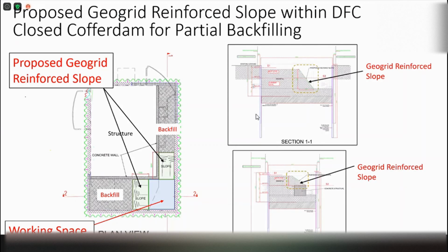So in this project, we are actually required to build a water pipe in the marina area. So this is actually part of the Marina East Desalination Plant project, where we actually have to do a lot of temporary excavation work for pipe laying. So in one of the particular cases of the pipe laying, we actually require to maintain a slope within the excavation. Yeah. But the slope needs to be a very steep angle within the excavation. So this is not a permanent slope. It's just a temporary slope.